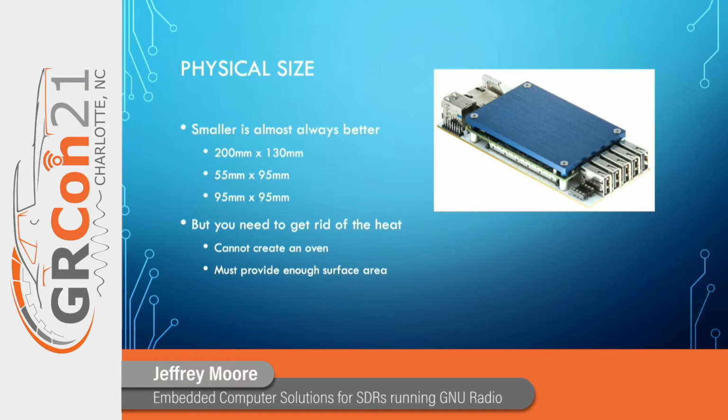You would typically mount this to a chassis or even the enclosure of your product, where this board is inside the product. And that aluminum plate is thermally connected to the hottest chip or chips on the processor module. And this is anodized aluminum because anodized aluminum actually has better heat transfer characteristics than raw aluminum.